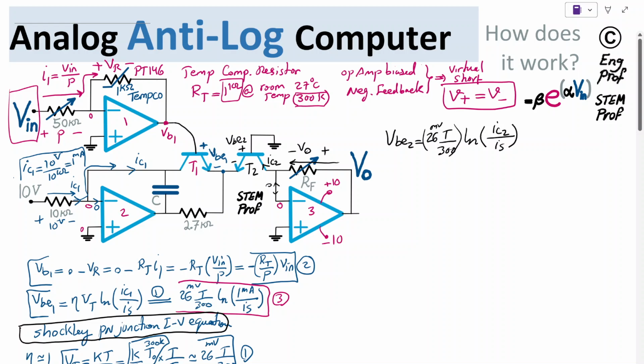So we can compute IC2 easily: IC2 is equal to Vout divided by RF. So here I'm going to substitute. Therefore VBE2 is equal to 26 millivolt T over 300 times log of Vout over RF divided by IS.